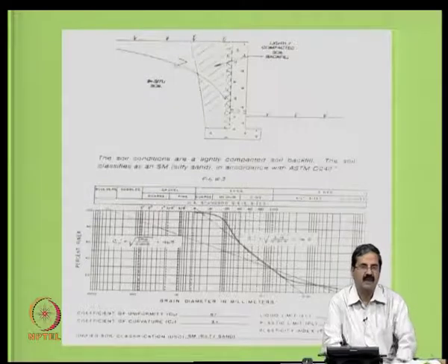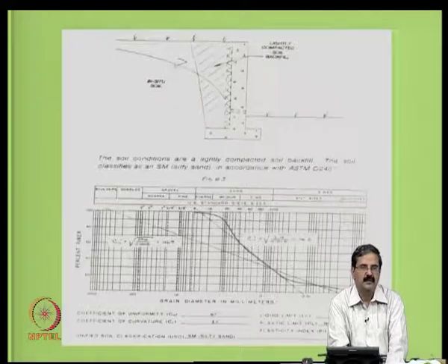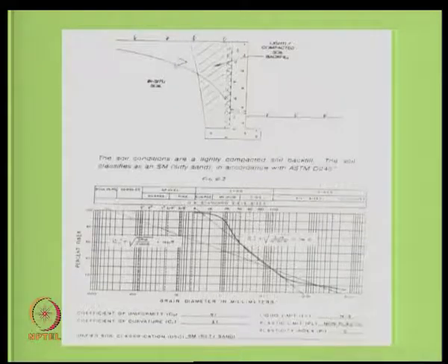one RE wall had a failure. They felt that the failure was because of the drainage, because according to one of the contestants, the contractor did not provide geotextile there. The other group says that he has provided only the gravel, and that is sufficient. He need not provide geotextile.